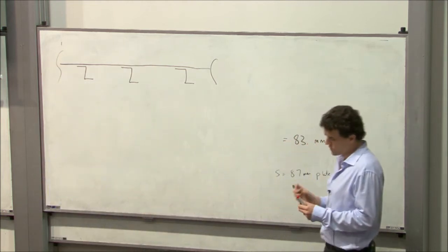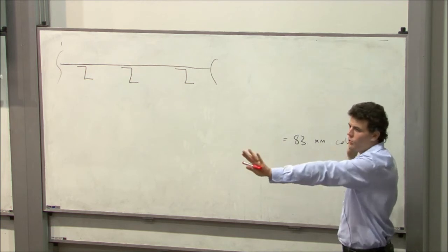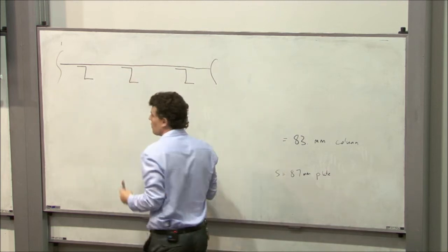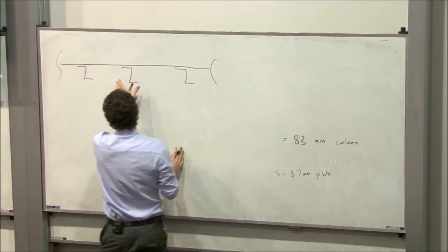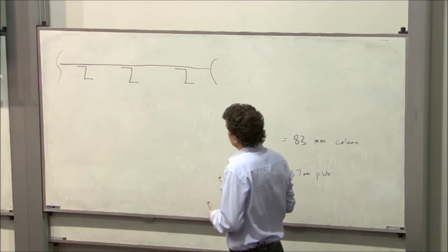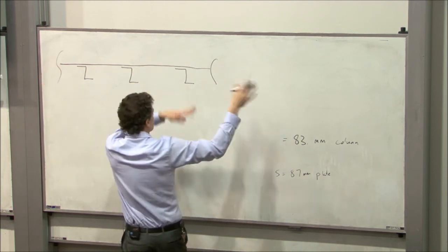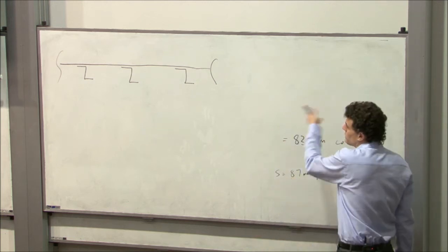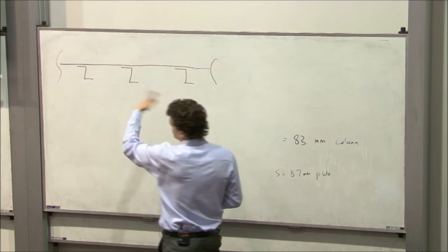Okay, so most of these analyses assume that the panel is just a constant repeating unit of an unknown width, because we generally look at loads for a particular stiffener or stresses. We don't need to know the total load for the whole panel because we have ways of normalizing. If we know how much load a stiffener can carry, we can easily just multiply by the number of stiffeners in the structure. So the simplification that we use is that our panel is flat and that it's a constant repeating unit off to infinity. And we never try and calculate the total buckling load for the panel because we don't know how wide it is. We only ever calculate either the buckling load for the column or a stress.